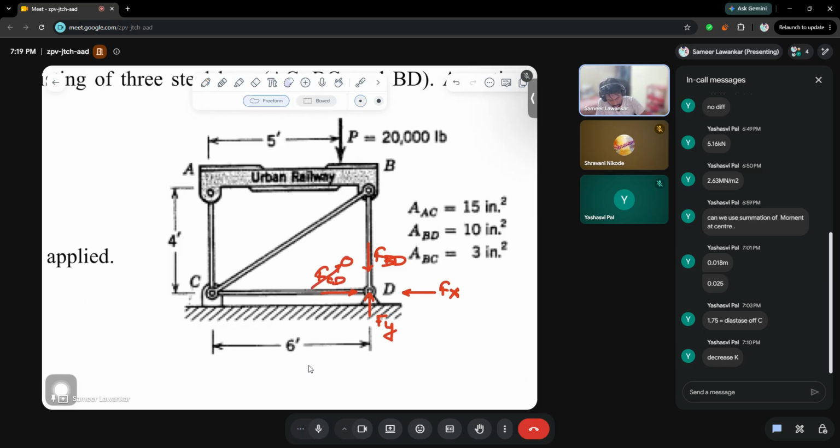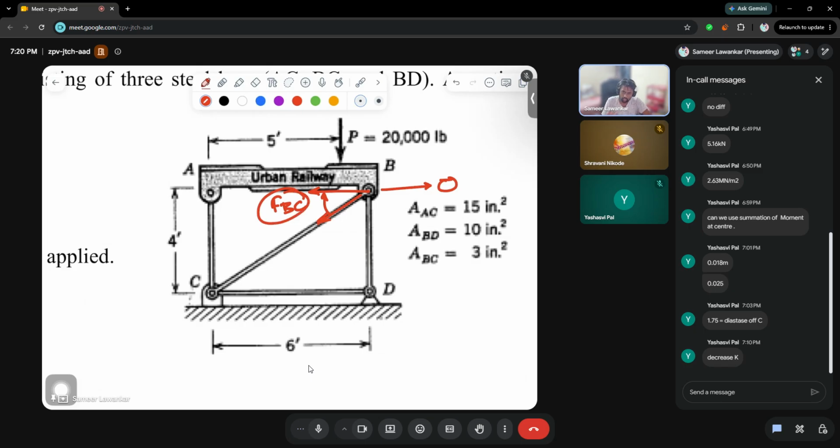Okay, similarly for this point, if we actually calculate again, rigid will not have anything to do with forces up here. What is the value of FBC? FBC is in this direction. Now if you take the component of this in this direction and sum it with the external value which is 0, this is nothing but FBC, and if we do summation Fx equal to 0 up here, we again get FBC is nothing but equal to 0. The force in FBC is 0. Whether it is deflecting, whether it has some value of delta or not, we will look at afterwards. Okay.